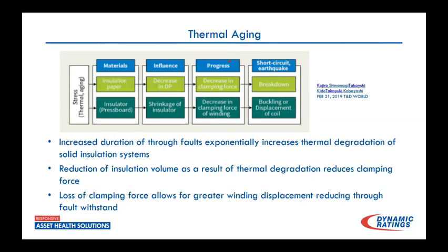So the only way you would really be able to catch this type of event with any kind of accuracy would be SFRA testing. You would have to have a good representative SFRA initially of that transformer in good health, and then after these type of events, you would have to run another SFRA, or you would have to make that part of that cyclic testing that we do on transformers to start seeing these changes in their inception.